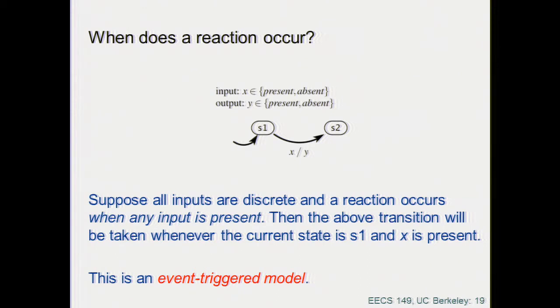The clock, right? The infamous clock. The clock is a time reference that produces that trigger. It's still triggered, right? It's event triggered, but on one particular event, that is the clock. And that is a way in which you trick an essentially asynchronous system to behave synchronously.